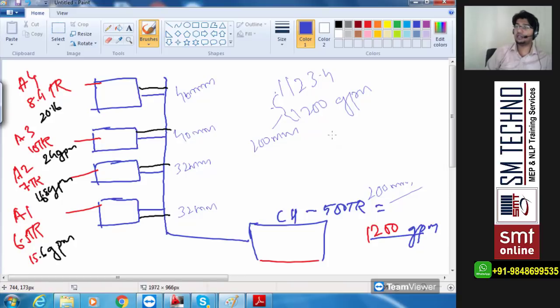We will consider the pipe size depending upon the capacity of the chiller first. Later, in the segment where the AHUs are, if you have the capacity to reduce the pipe size, do so depending on the 4 calculated AHUs.